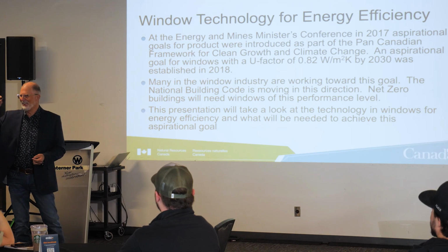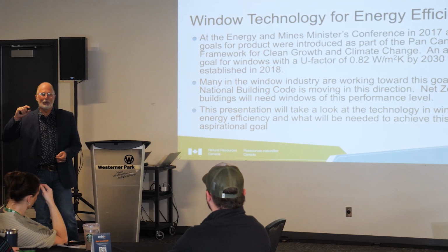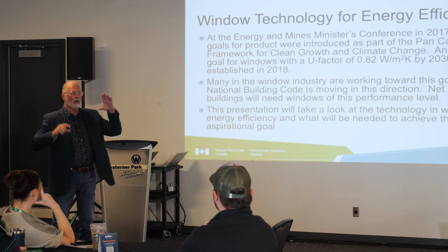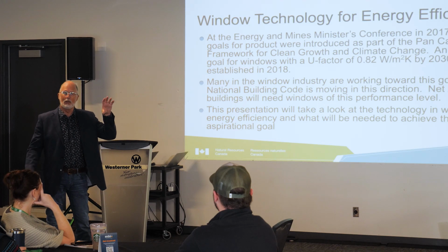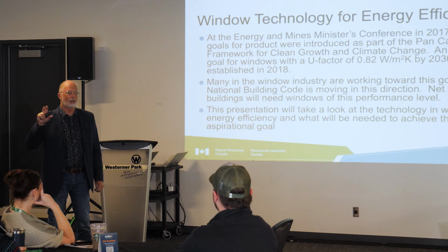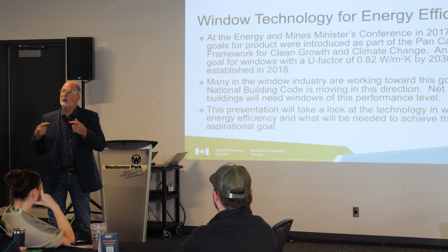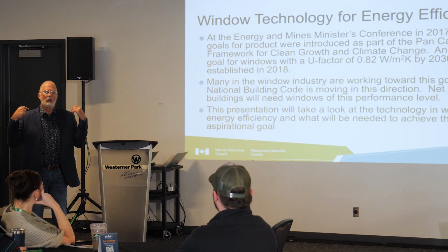Yeah, very little, right? So, what would make the better impact? Would it be putting more insulation on the wall? Or would it be getting that window up as close to that R16 as possible? If you had an R16 window, you wouldn't be adding any extra insulation to your walls. Your building would perform really well. But what's interesting is, have you ever modeled a house and taken all the windows out of it?